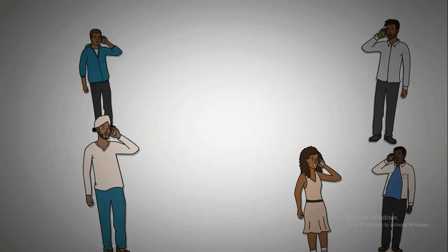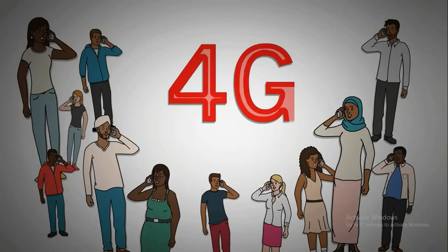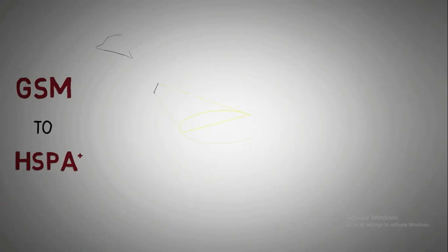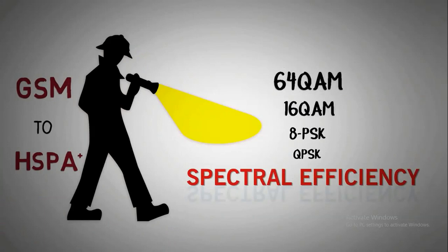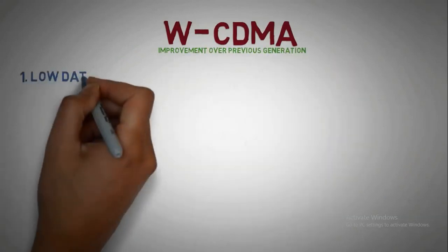As the number of users and their demand started growing, communication networks evolved from 1G to 4G. The radio part was significantly enhanced from GSM to HSPA+. Now, focus shifted towards better spectral efficiency by using higher modulation orders like QPSK, 8PSK, 16QAM, 64QAM, etc. WCDMA improved upon some of the problems of earlier generations, like, first, low data rates.